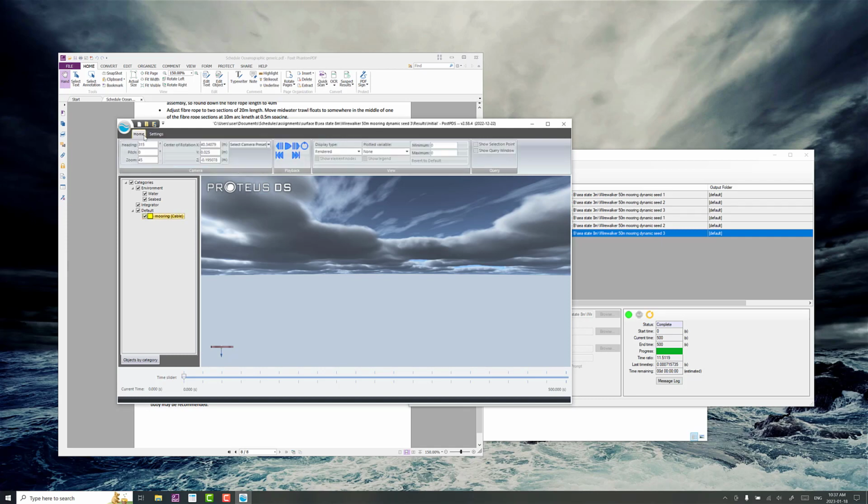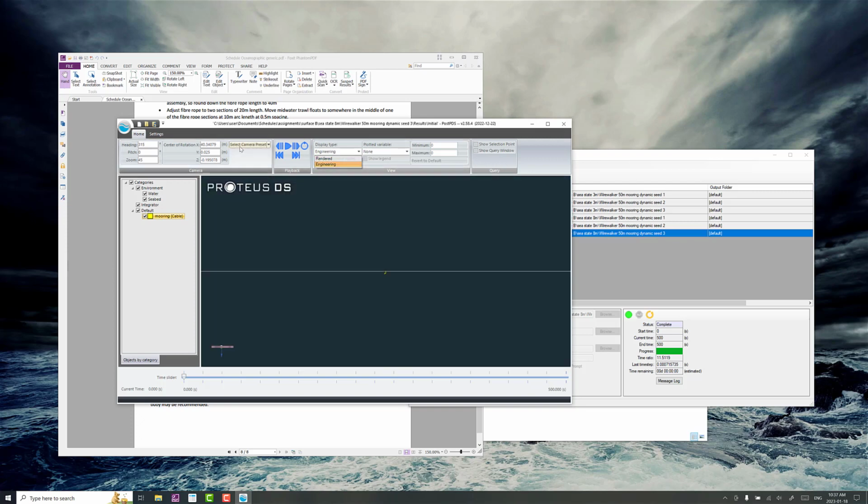So we got orthographic view on, let's change to engineering and then east. So that's the way the wave propagation and current are aligned, going from the left of the screen to the right. There's our downweight. And just very generally, we want to make sure the downweight's clear of the seabed, and things are looking pretty good, and generally the mooring is absorbing the motion from the surface wave, so that's good to see.